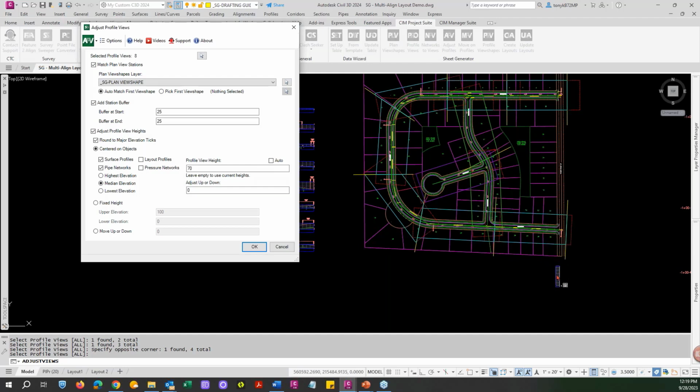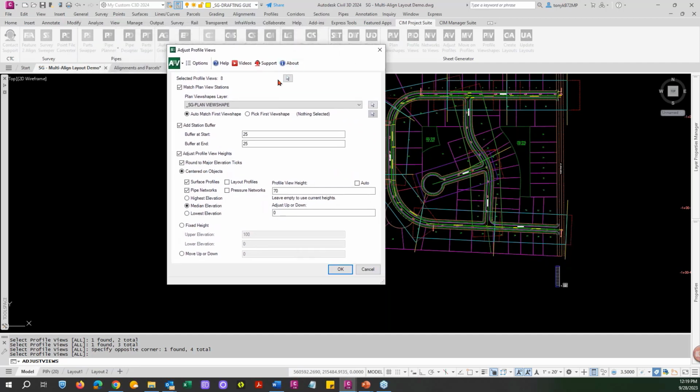This block that we have here, our masking block that we created, which again I can share with you. And then the height of this matches what I can fit in my view for a 20 scale, which is what we're doing today. So that would be the only thing you probably want to change, is if you had 30 scale or whatever, you might need a new block for each of those. But that's why that's there.